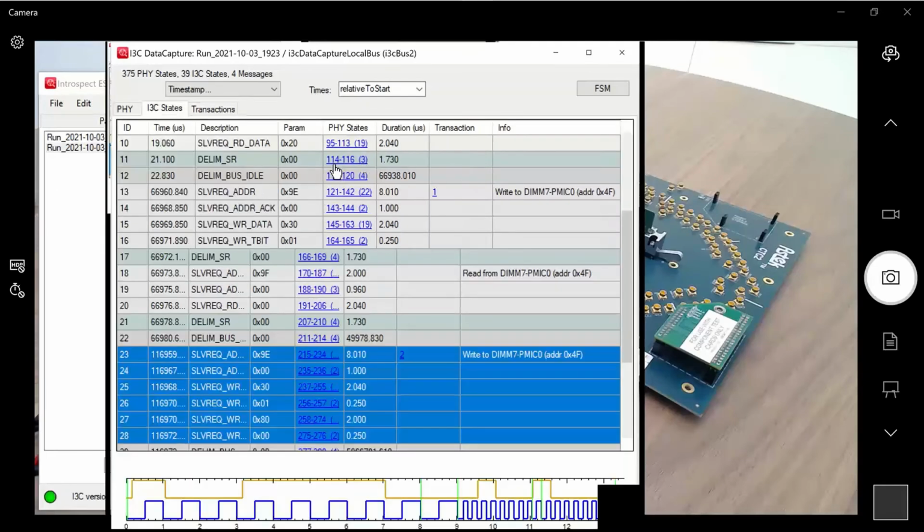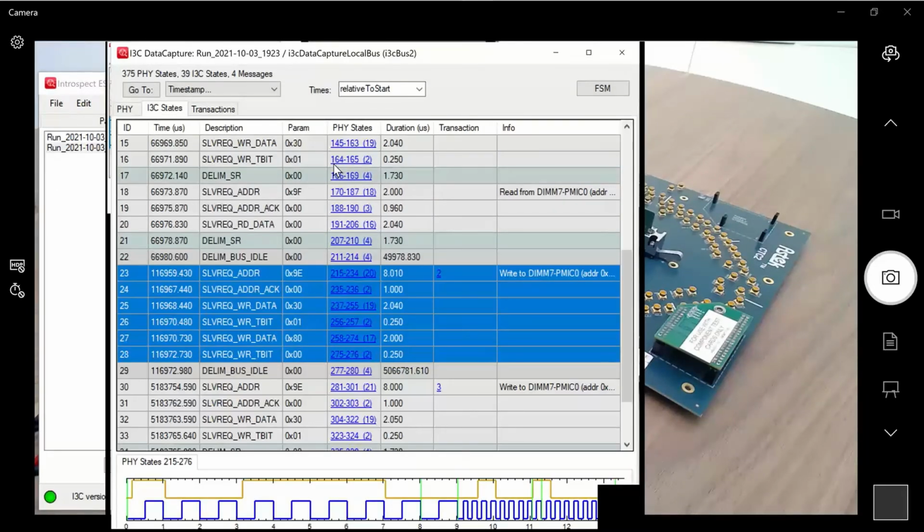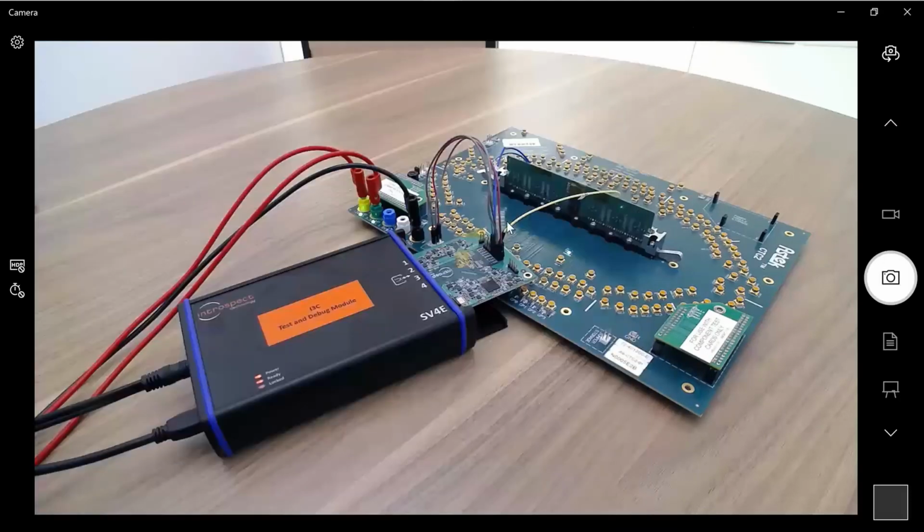And so this is a really powerful feature of the SV4E I3C, because you can be using one port to just be exercising, and then the protocol analyzer port is a completely orthogonal tool that's just attaching to any of the ports on the SV4E I3C, and that can measure them. So if we declare two ports where one port is doing the exercising with this red wire, and then the other port with the green wire here is just doing the probing, you're able to interface with both sides of the SPD hub using a single instrument and without having to go acquire other probes or other tools.